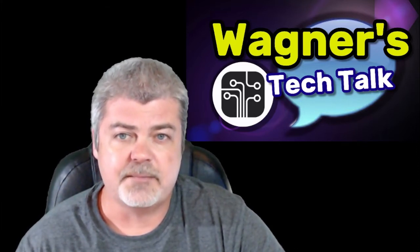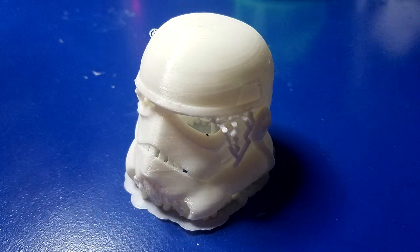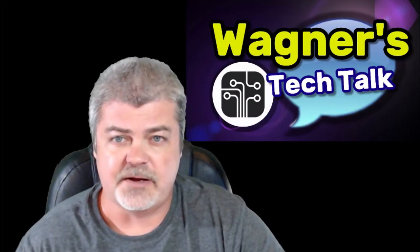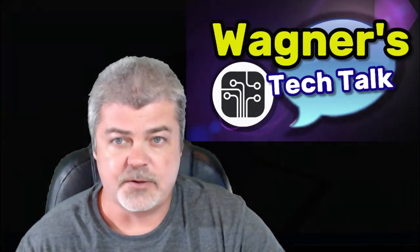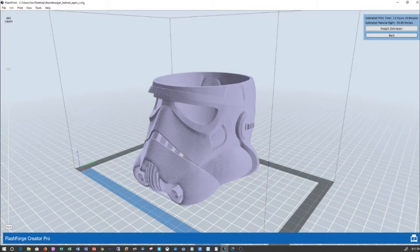The first step of 3D printing involves creating or acquiring a 3D model, which is commonly an STL file. The STL file basically has all the instructions needed to recreate the model, used by another piece of software called the slicer. You don't have to design your own models in order to use a 3D printer.